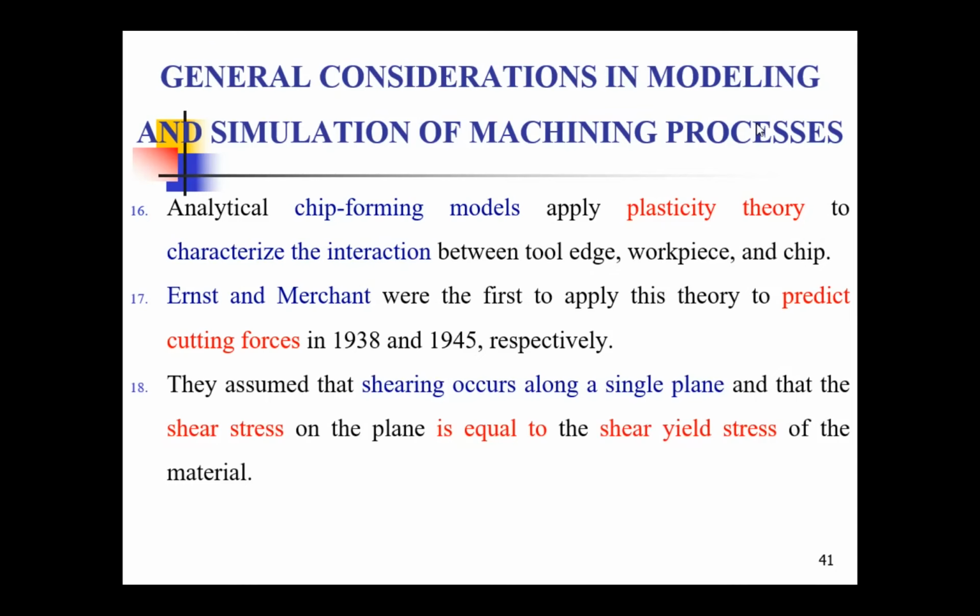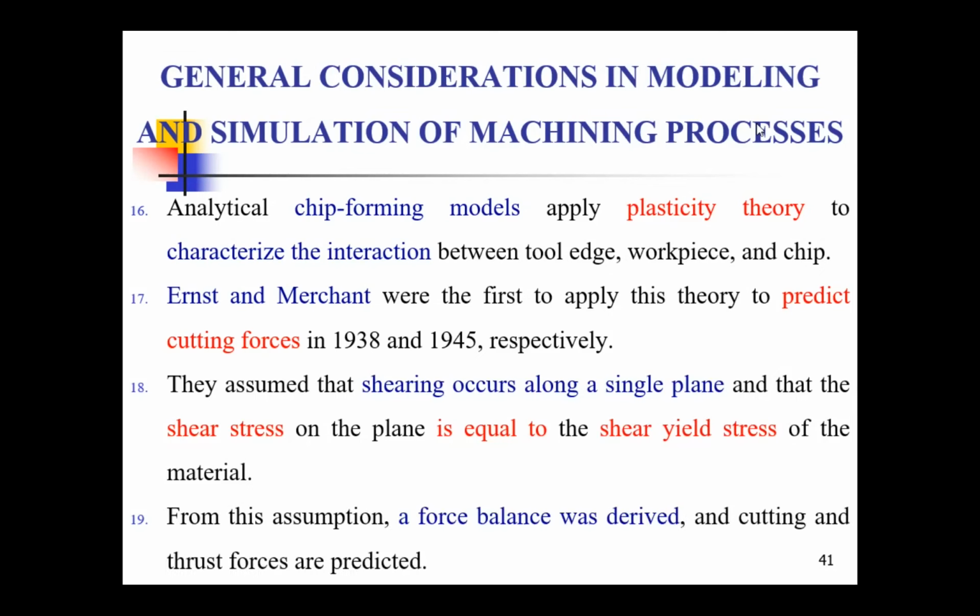This statement we have seen in the shear plane model itself. That is the work of Ernst and Merchant. By using this, that is, shear stress equal to the shear yield stress in the shear plane, a force balance was derived, and cutting and thrust forces were predicted. So based on these assumptions, we are going to predict the cutting forces.